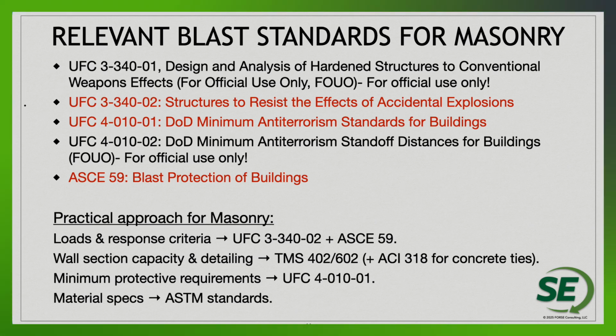Also, of course, it's important to note that the practical approach for masonry includes obtaining loads and response criteria from UFC 3-340-02 and ASCE 59. But then anything that has to do with capacity and detailing goes back to TMS 402-602.